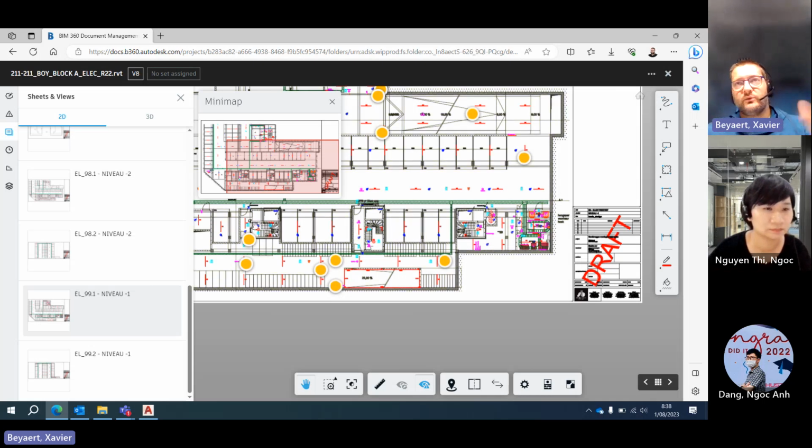I mean, you have, for example, the feeding of the elevator for, let's say, staircase one, and then you have lighting, you have sockets. Put that together, and then you have that three times. So if we need, we can put a counter before it, and we see the consumption of that part of the building. Yeah, a bit of a logical build-up of the installation.